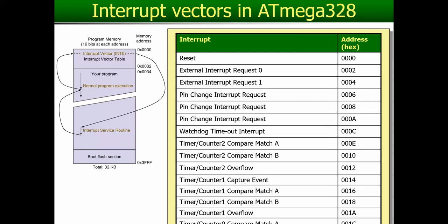I repeat, you're in a normal execution mode. You were interrupted externally, and that INT0 pin, and from there you note down this address called 0002. From there, we jump to 0002 automatically, and from that 0002 we will be directed to, for example, a jump instruction, directed to go here. And that happens in case of all these interrupts that you see on the screen.